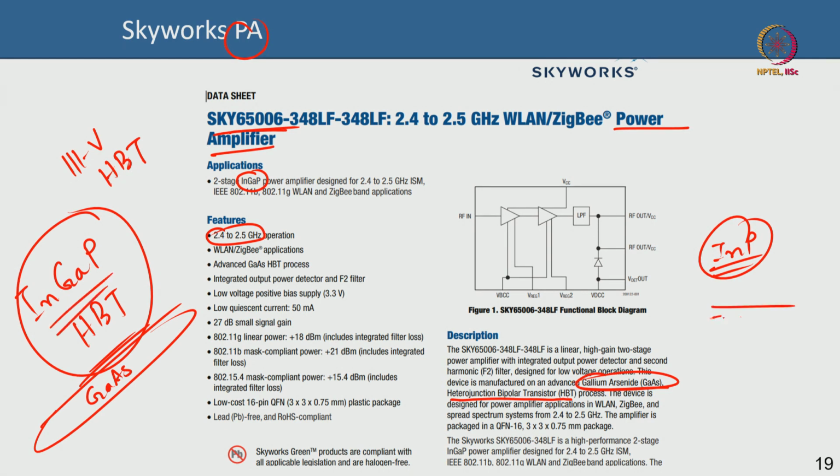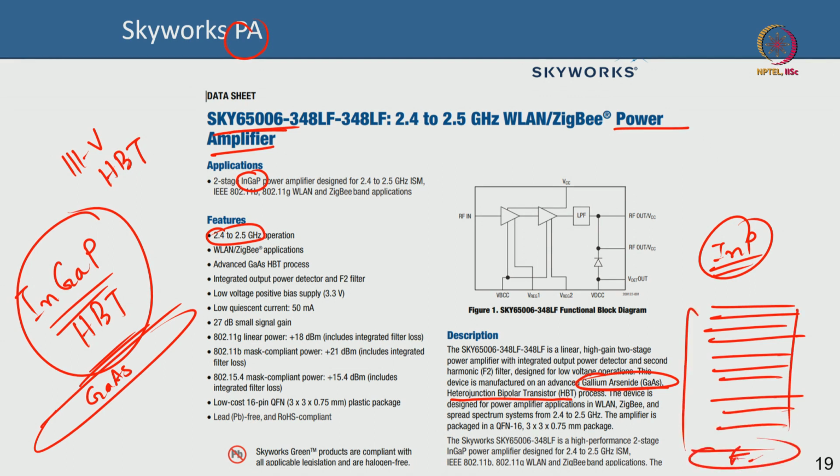So, there are many layers, the emitter might be a stack of layers, then base, then collector, sub collector, all these things are built on a gallium arsenide platform. The top emitter could be the indium gallium phosphide emitter, of course the topmost part will still be N++ gallium arsenide or something to make a low contact to the emitter. But an indium gallium phosphide heterojunction bipolar transistor is used in this power amplifier that goes in an iPhone 12 Pro Max that we found out here.